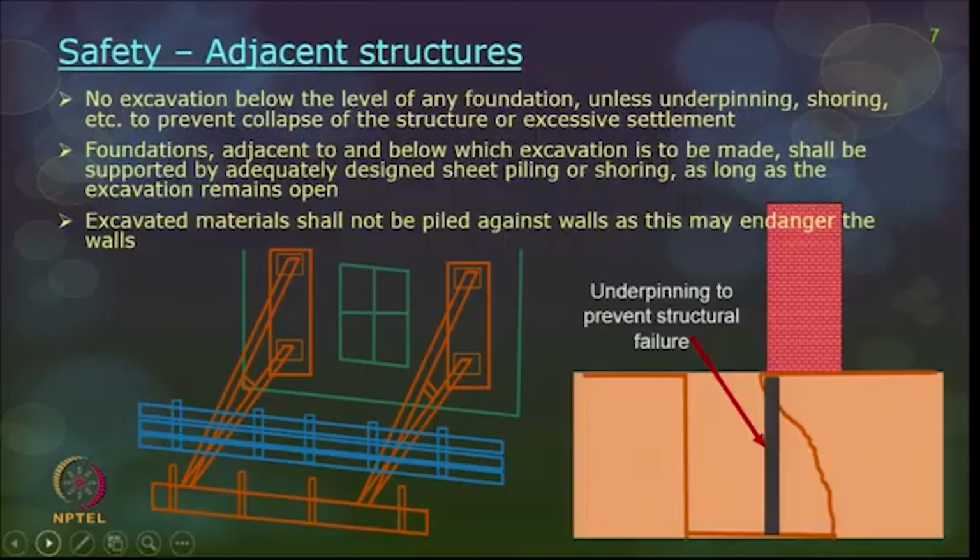No excavation work shall happen below the level of any foundation unless underpinning is done. Underpinning is providing additional support below the structure so that the structure does not fall off. These are the pictures of shoring, to prevent collapse of the structure or excessive settlement.